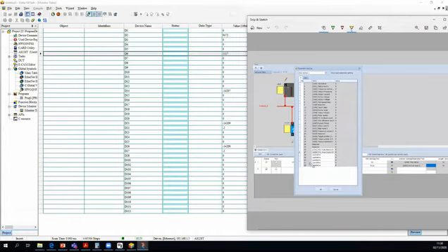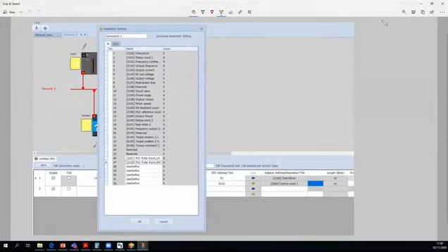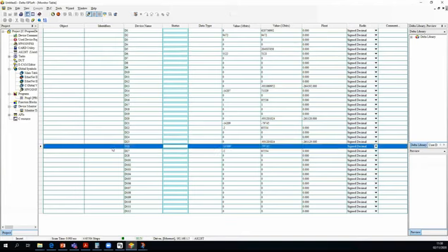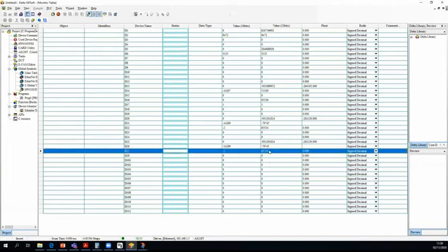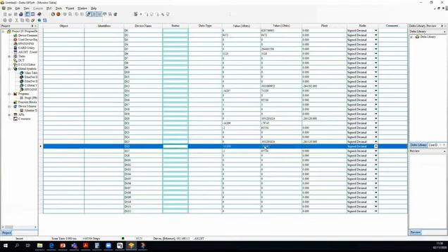And on D26 and D27, I should have the actual motor position. You can see here D26, the low word, and D27, the high word. And if you check here, you can see the actual motor position. Since you can read it also as a 32-bit value, you can see that the current position of the motor is minus 79,745.